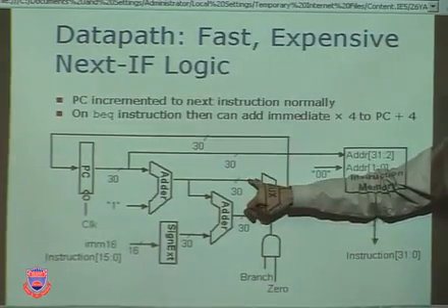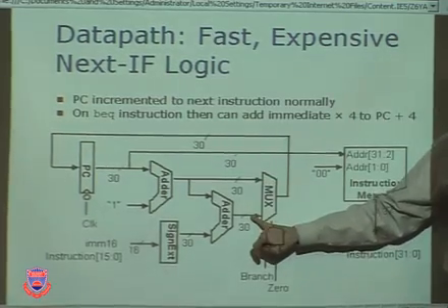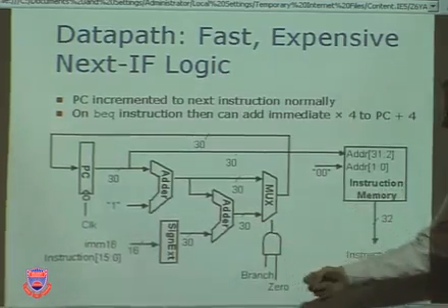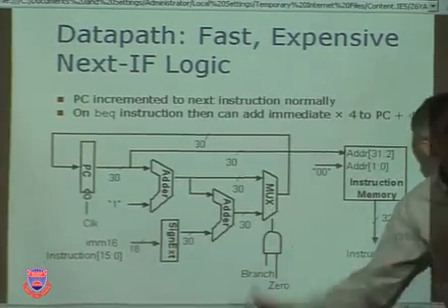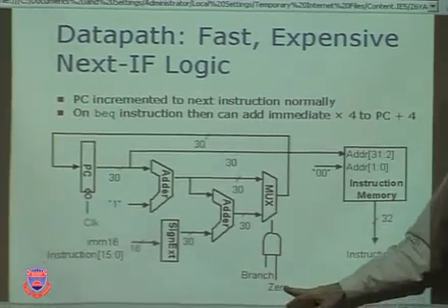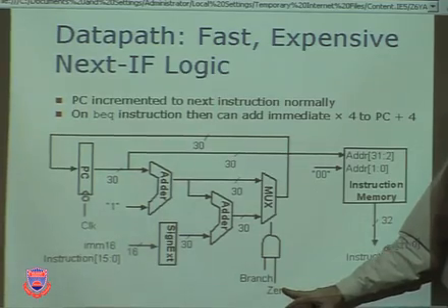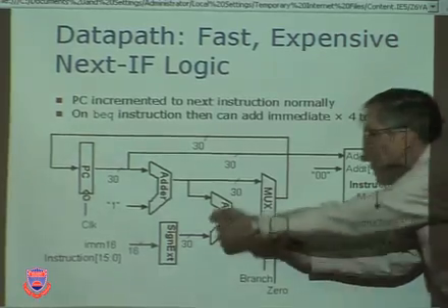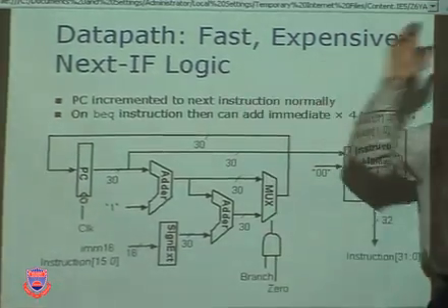So you could say this is the sequential next address. Since we're discussing what happens if you branch, all of us can guess ahead a little bit and say, oh, well then that must be the branch target address. And we'll decide to take it or not based on a decision of the mux. So what will we decide? Well, if it's a branch instruction, and if the difference between the two registers you're comparing is 0, it means they're equal. And so if it's a branch if equal, and they are equal, then you should take the branch, which means take that one. But if either of those is not true, you should take that one. Okay, so there we go.